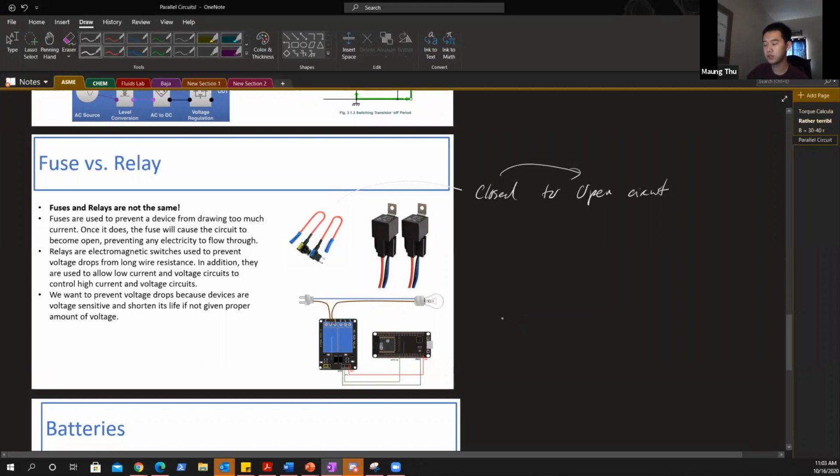They're mostly used in automotive because we have electronics that go everywhere in the car. So you need to use long wires, but long wires mean you're going to have voltage drop because there's internal resistance in your wire. Let's just say you have a battery here, and an electronic here, like 30 feet away, supplying 12 volts. What's going to end up here is probably 11 or 10.9 volts.